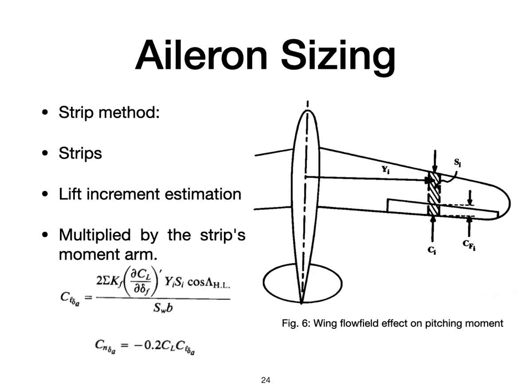Remember to reduce the aileron effectiveness about 15% if the hinge gap is not sealed. The yawing moment due to aileron deflection depends upon the spanwise distribution of induced drag with aileron deflection. This varies with the wing lift coefficient as well as the aileron deflection. Yawing moment due to aileron deflection can be approximated by the second equation, CL is the wing lift coefficient.